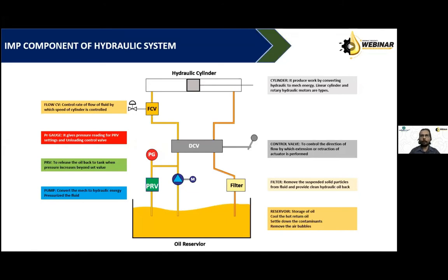Now, for precise control and smooth operation, we need a minimum gap between the spool surface and body. Sometimes they are in the range of 0.5 micron or 1 micron. So suppose our oil is very pure, what we call NAS 5 class.